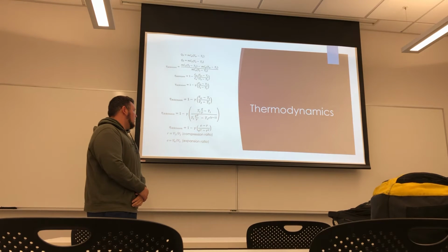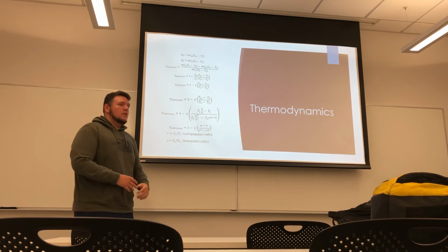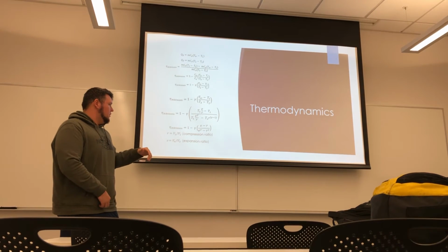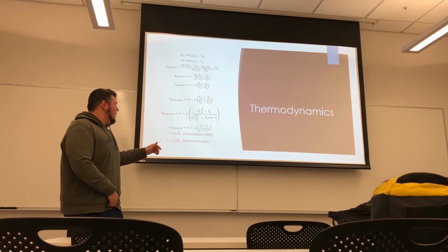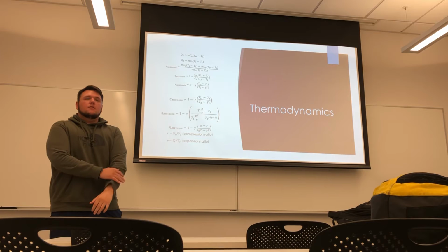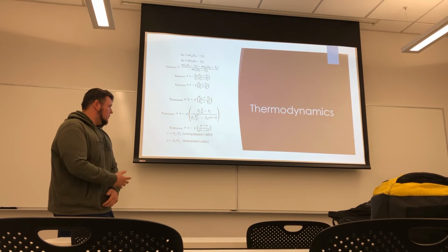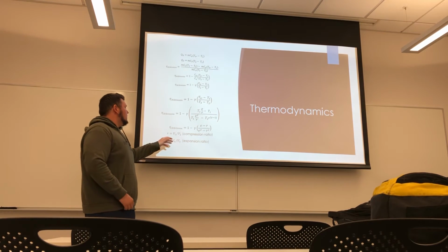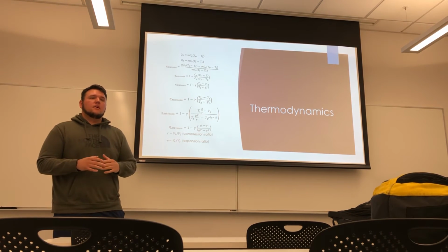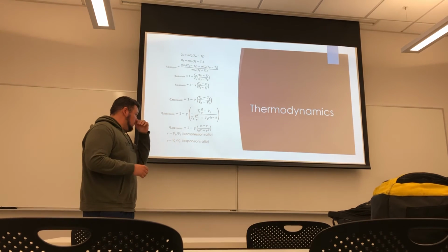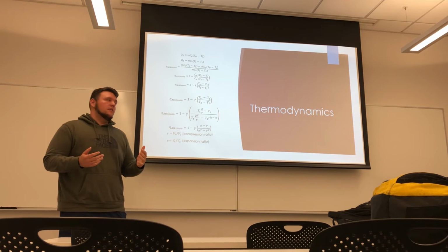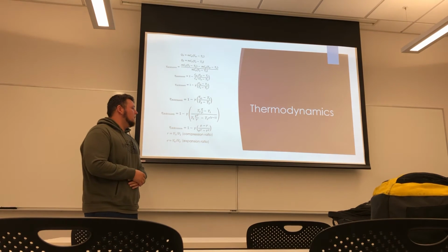And E and R, E is our expansion ratio, which is the volume of the exhaust stroke over the power stroke. And then R is our compression ratio, which is the volume of our intake stroke over our compression stroke. And since the expansion ratio is bigger in the Atkinson cycle, that's what makes the efficiency better in comparison to the Otto cycle.